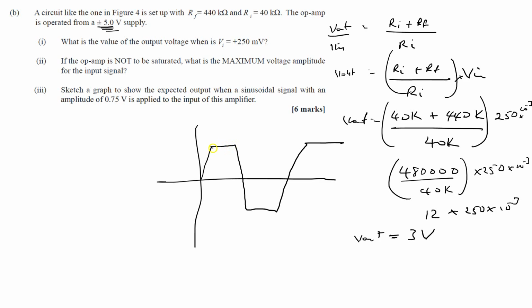Now, the reason for this flat region is because, generally speaking, the wave is alternating, right? And if the output is more than what the operational amplifier can supply, then it is going to perform a process that we call clipping. It's going to clip off the excess and basically clamp you to the amount that it can provide, which is plus or minus 5, right? So that is what you're seeing here. These parts are being clipped off.